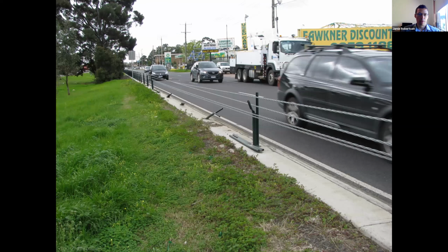This barrier has essentially a 0 offset from the edge of traffic lane, or a very small offset of a few hundred mil. It's struck repeatedly. It's a real maintenance burden. Probably the choice of barrier system is wrong here. It's a flexible wire rope, which is great from a safety point of view. From a maintenance point of view, it's a headache. If that was a W-beam system, it wouldn't need to be attended to nearly as frequently as it is.